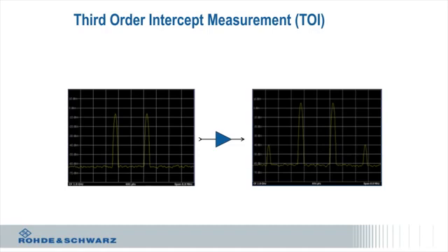Okay, so what does it look like when I measure it? Well, this is showing you an actual amplifier measured with a spectrum analyzer, and you can see I put 2 tones in, and I get the 2 tones out plus the 2 extra terms. Okay?